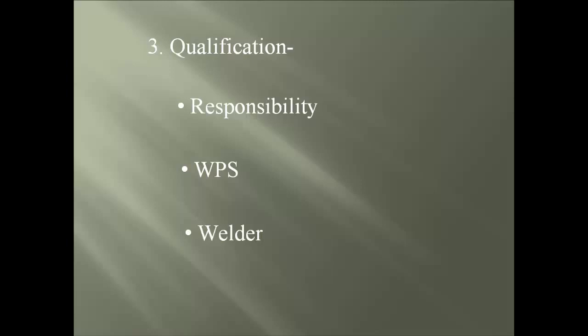Now are the welder qualification requirements, and this will determine the welder's ability to produce sound welds and not to guide the welder in the how-to for welding. The following are established during qualification: the welding process, material grouping. A quick tip: this does not qualify the welder to weld galvanized material. That will take a different qualification test to establish that.